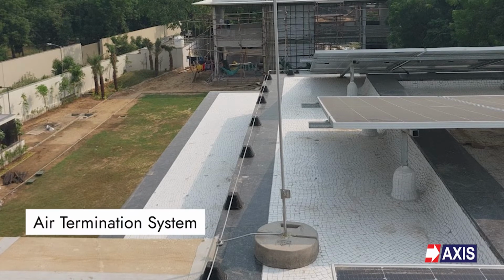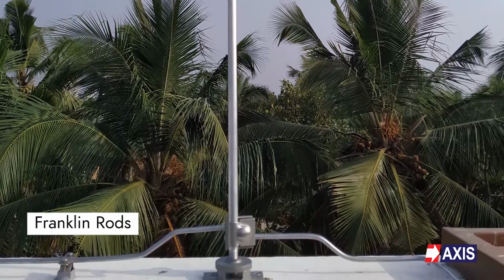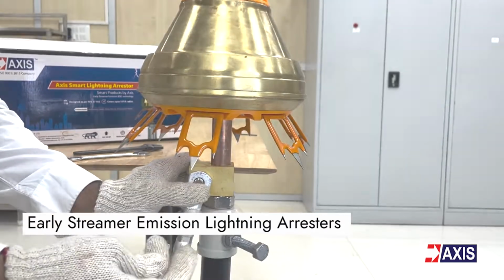First, the air termination. A variety of air termination systems can be used in conjunction with the rooftop solar plant depending on the dimensions and the materials needed in that space. These systems include the Franklin rods or conventional system, the early streamer emission or ESE lightning arrestors, the catenary wire system, or any other options.